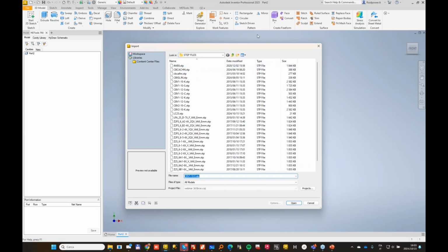It's better to import a step into a part, because if you open the step directly it may be an assembly, and then suddenly you get an assembly file. Normally, when we want to assemble valves or components with MDTools, we want to treat them as single items. So it's better to have parts. This will simplify dramatically the management in the assembly.